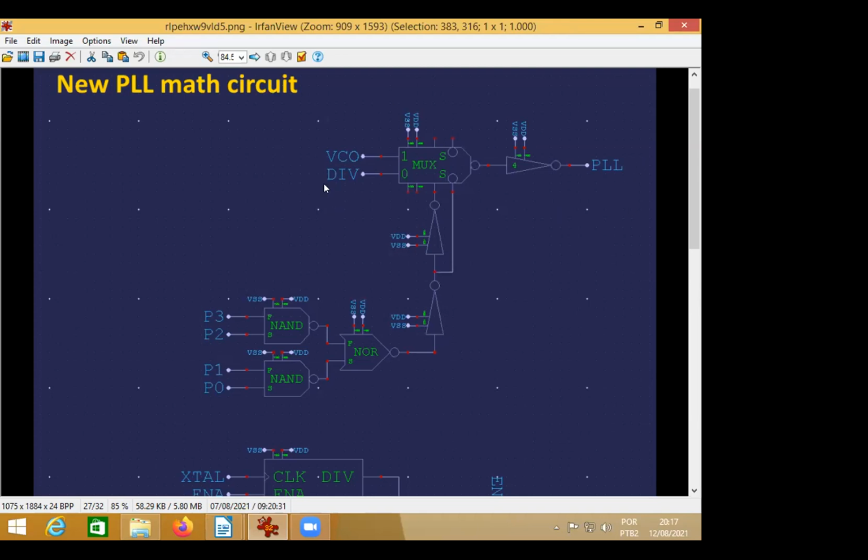But if you can ensure, not using exactly that mux, that you are injecting the faster clock VCO into the middle of a string of high bits, you are sure you are not upsetting anything, because any glitch will be masked by the other branch of the ORs.